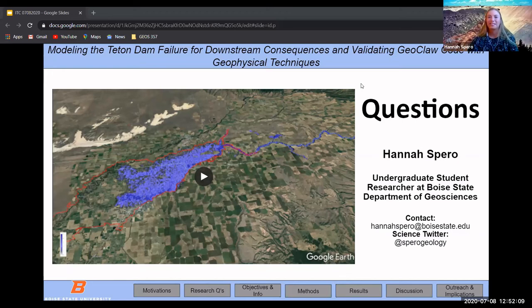Devin, great questions today. So I'll answer that in two parts again. So the Manning values based on depth of flow and how that would incorporate into the uncertainty. I believe that was the question. So there is a significant amount of uncertainty in the model already. And the nice part about depth is this area is generally flat. If there was high sloping topography, our uncertainty would definitely increase.